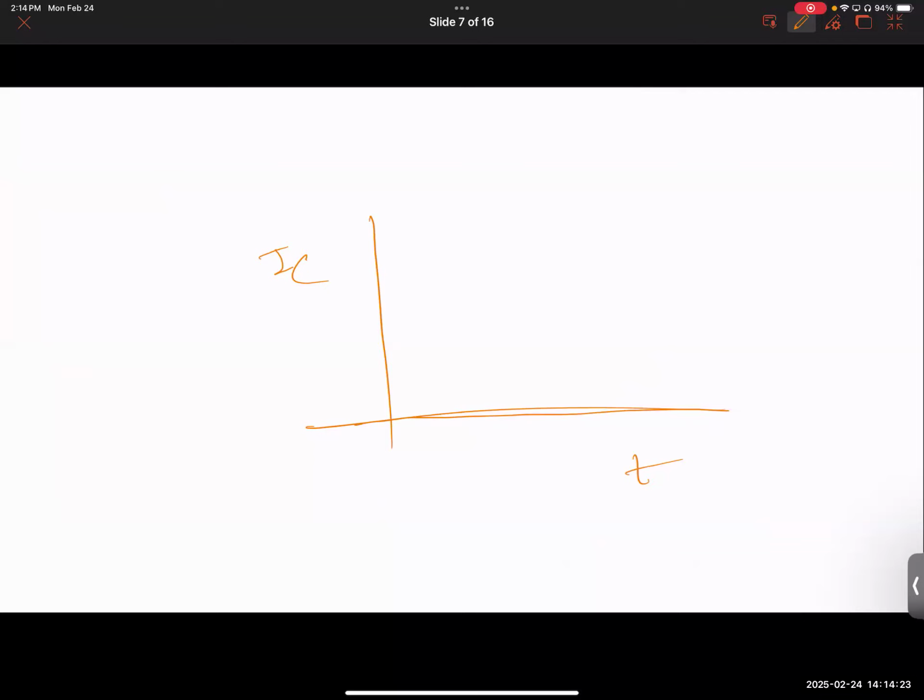If you give a magnetic tunnel junction a lot of time, then even with a small amount of current, you'll be able to switch it. But if you reduce the time, you'll need an exponentially high amount of current to switch. This is how it looks in practice. All with me? So if I want to make it really fast, you have to apply really high current.